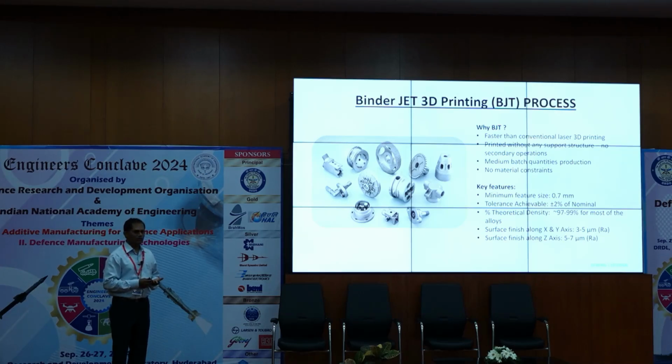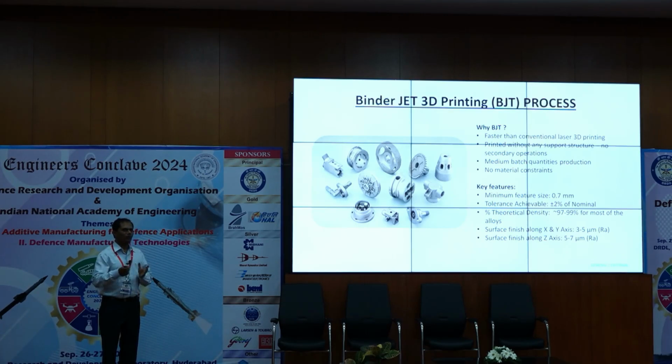Here you can go for ceramics, you can go for cements, like we have made some tungsten carbide materials, ceramic materials, different tool steel materials like M2, which is very high carbon material. Name any material, you can process it through this technology. Depending upon how you choose the material composition, particle size distribution, and the sintering profile, you can get close to 99% of the theoretical density. Even with heating, you can go close to 100% density.